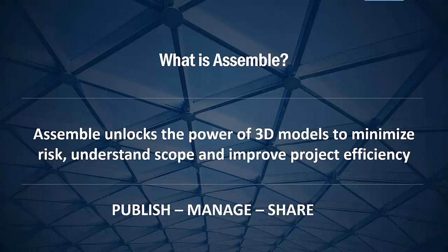For estimating purposes, which is what we're focusing on today, you have the ability to aggregate different quantities based on different property sets. So if you're interested in looking at the total cubic yards of concrete, you can set up your data so that you can organize it and get that information out very quickly. Once you do that, you have the ability to share it across your project team. Melinda and David today are talking about their use and how they ultimately share with the rest of their team. So with that said, Melinda, you want to go ahead and jump right in?